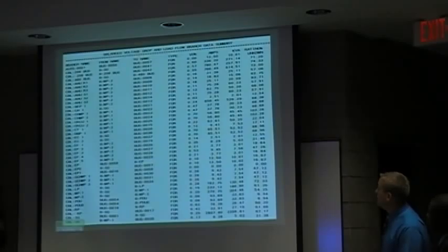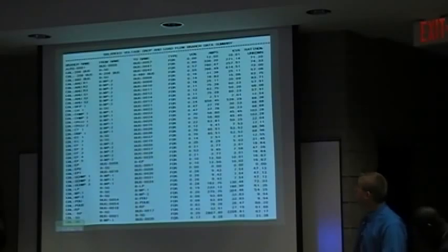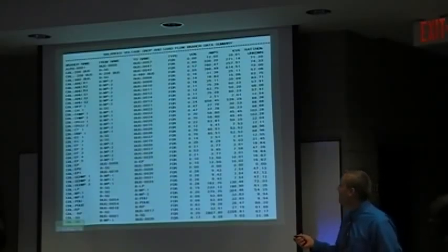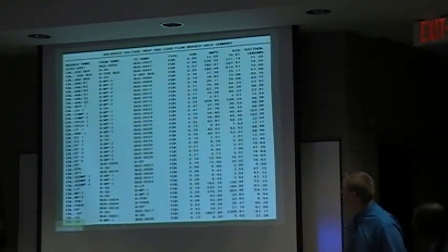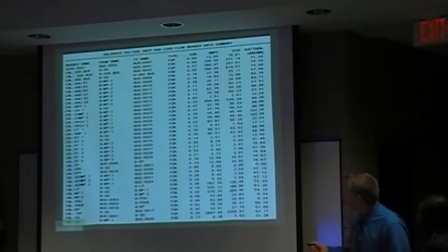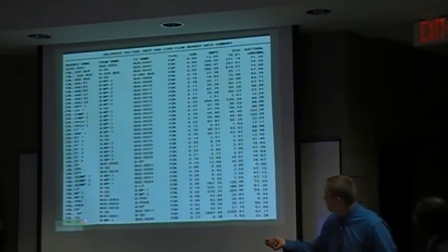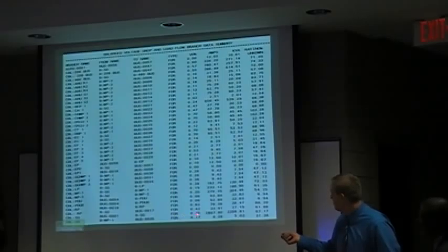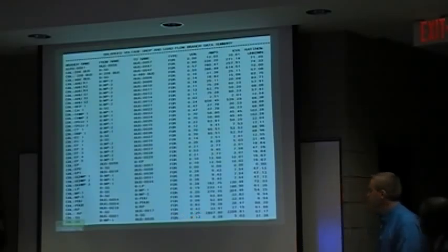This is the balanced summary of the voltage drop and load flow. I'm not going to run through everything here, but just to highlight a couple of things. Our computer room cooling unit, if you move over to here, is running at a voltage drop of 0.7. Another big one here is our switchgear. The voltage drop for that is 0.25, so not much volt drop happening there.